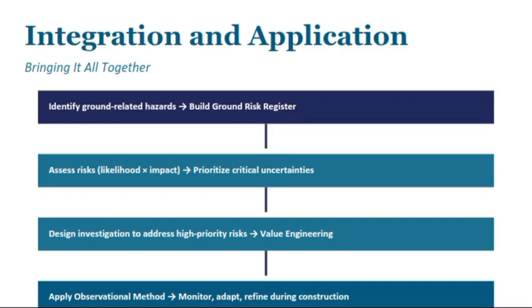Then you go into the investigation strategy, which will include CPTU, boreholes, geophysics, and groundwater monitoring. When you monitor the groundwater, you can be sure of the exact level where the groundwater table is. You can get the exact levels. From the geophysics, you can tell a lot of things happening in the subsurface. And then we have the observational method. Yes, the observational method can support the staged foundation design. As you're doing it, after doing all these things, you now begin to have your observational method.